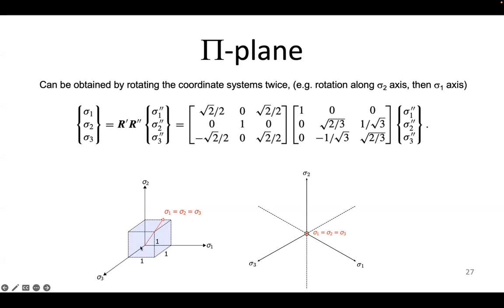In order to reach that 1, 1, 1 line, in order to go from the orthogonal to the piping, to the hydrostatic axis. The hydrostatic axis is the axis where sigma 1 equals sigma 3. I want this to point to my eyes directly. I want to look at it this way. In order to actually do that, I first rotate this into these directions. That is 45 degrees on the 1-3 plane, right? So that's why you have this.